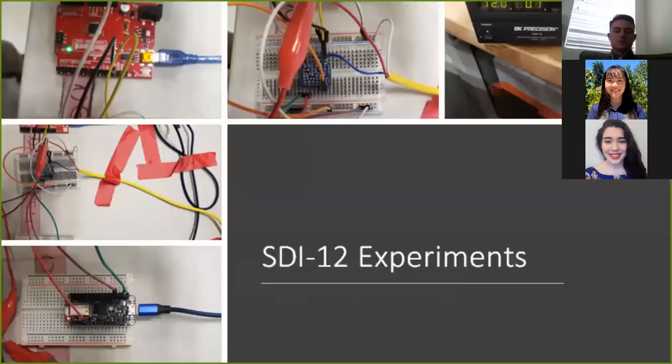I also did some SDI12 experiments, so the sensor experiments. Originally, I used the breadboard, but we changed that at the very end to use the Nano. And then the Nano connects to the SDI12 bus. We do a logic convert between 5 volts to 3 volts, which is necessary to communicate between the microcontrollers. We send that over, and then we have that information ready to go.